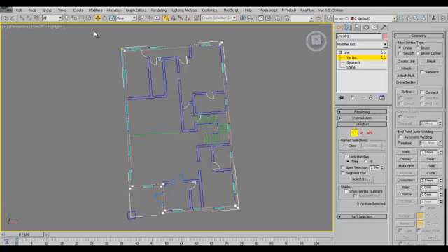So what I actually do all the time, once I have something like this and I'm not sure if it's closed or not, is select every vertex and tell it to weld. Once I weld that, you can see it has chosen this point, because this was the open loop, and it has chosen it as the yellow point and closed it. So we have a closed spline here.